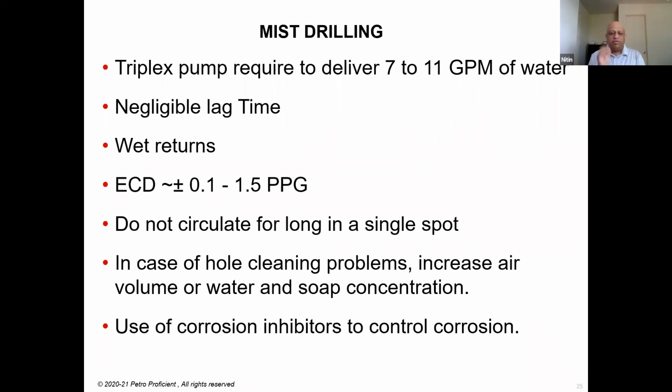So they are not like how we saw before as dust, but they are now slightly wet because you now have water in the air. So this water will cause wet samples to return. And some of the recommendations are not to circulate for long in a single spot, to ensure that the hole is clean, and you may have to increase the air volume and the concentration of foaming agent and water depending on the requirement. So this comes with experience, judgment, and some engineering knowledge. Most of the time, the supervisors and service companies that come to do this job have a lot of experience in this, and they will adjust the parameters to ensure that you don't have any downhole complications typically.